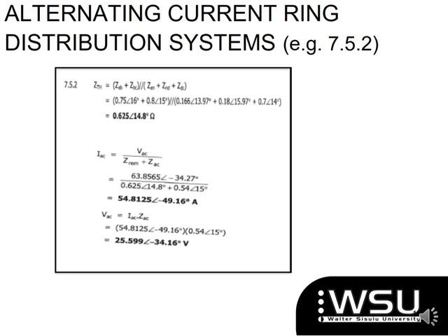And you can see now with your interconnector, like you were having at your DC section, your Z Thevenin is going to subdivide those. It makes the top part and the bottom part parallel together. All right. So therefore, the top is going to be the ZAB plus ZBC. Then the bottom is going to be your ZAN plus my ZND plus my ZDC. And I get my Thevenin equivalent circuit there.